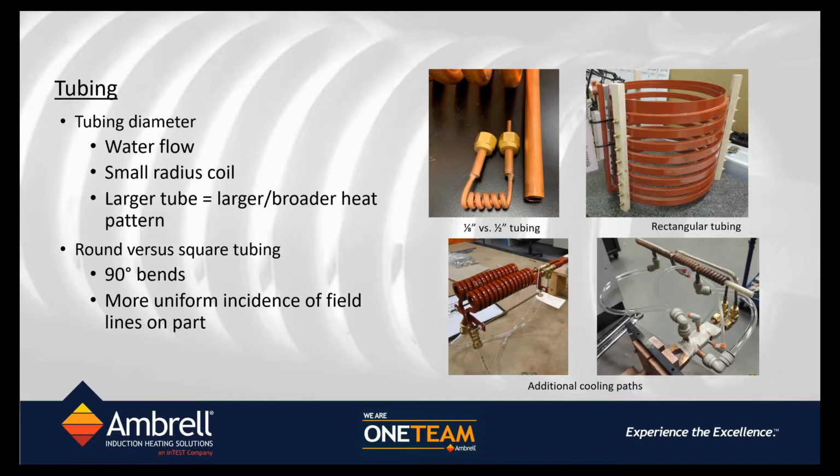Well, if the coil is not cooled because the water is heating up, the induction heating coil will heat up and basically burn and melt. So it's important to determine how many turns you need and what size of copper tubing would be required.